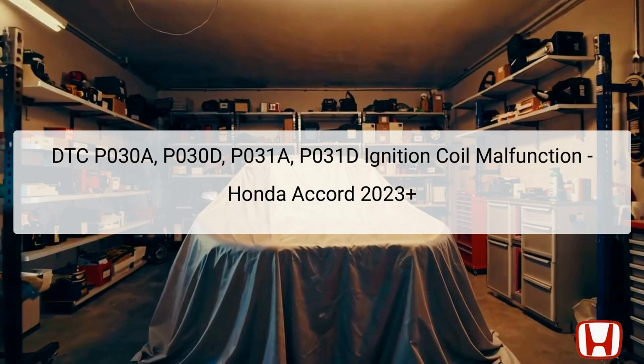In this presentation, we will discuss the diagnostic trouble codes DTCs P030A, P030D, P031A, and P031D pertaining to the ignition coil malfunction in the Honda Accord 2023 and later models. These codes indicate a malfunction in the ignition coil circuit within specific cylinders. P030A for the number 1 cylinder, P030D for the number 2 cylinder, P031A for the number 3 cylinder, and P031D for the number 4 cylinder.